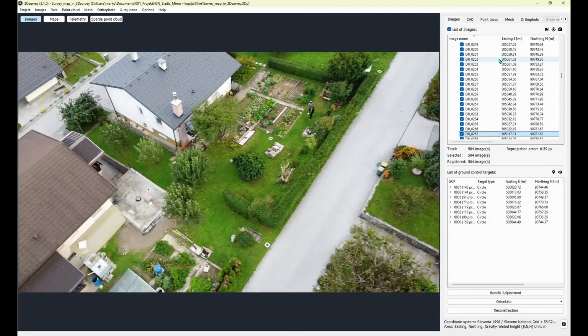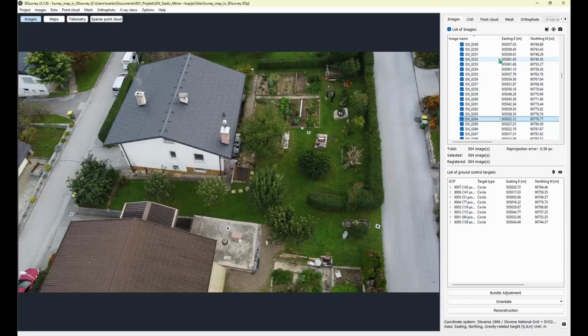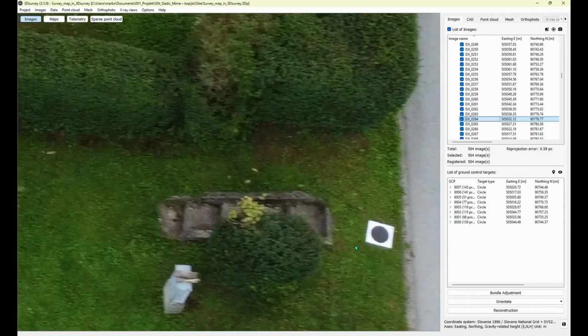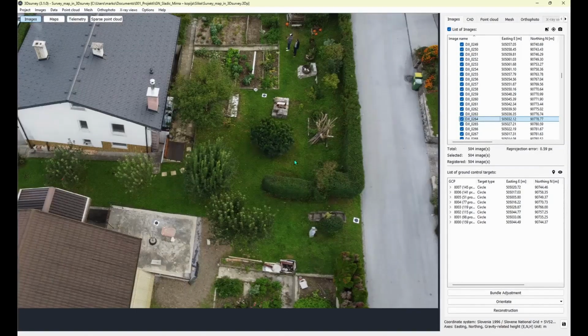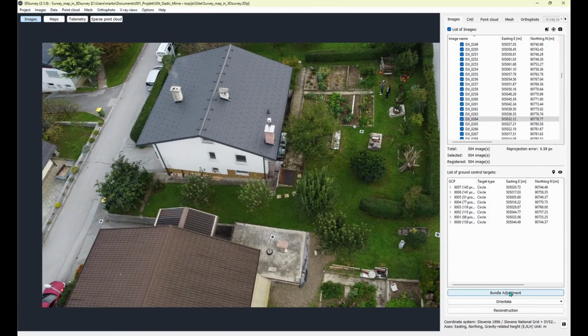But nevertheless, we were able to get images which are good enough to calculate a 3D model later on. Because the drone does not have an RTK antenna, we use 8 ground control points to do the orientation of the model. We placed 3Dsurvey ground control point targets, which help us with the orientation because it's almost fully automatic. And then based on these images, we first calculate the bundle adjustment, which gave us the basic model.